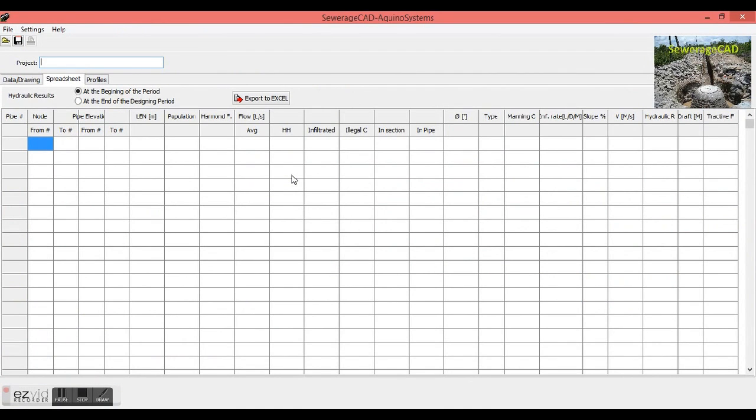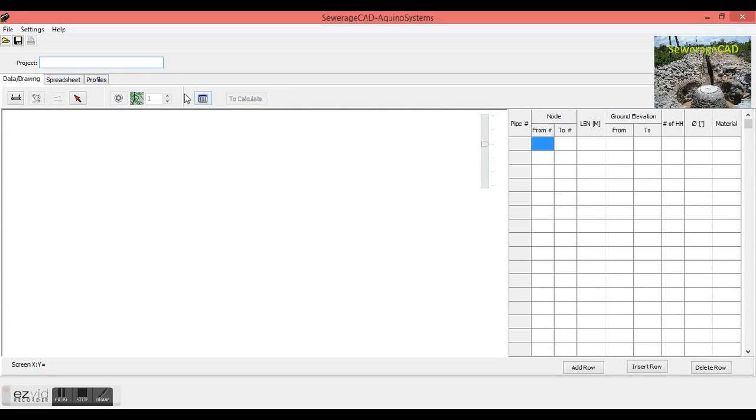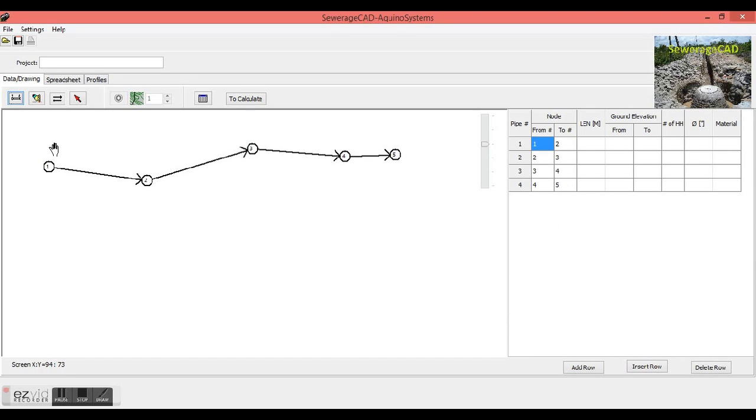The main screen of the program presents a paint box, which will be used to draw manually the scheme of the sewer network. We can draw the branches just by clicking to place the manholes. By double clicking, the branch will be closed. We can also add branches by clicking near the node where we want to start a new branch.